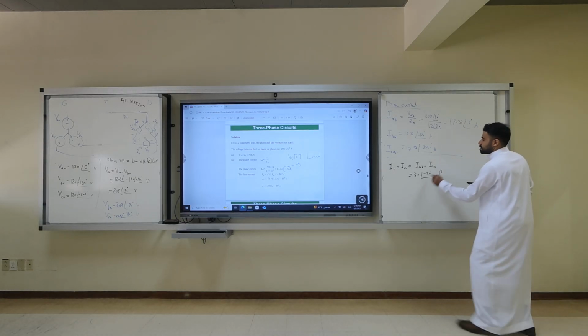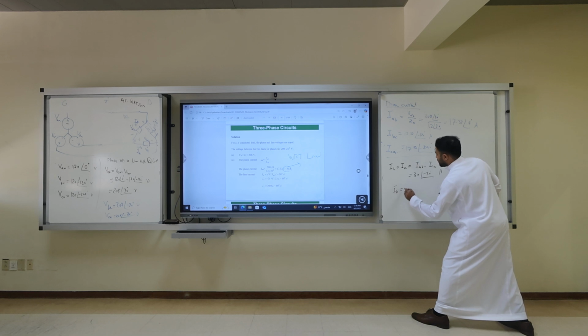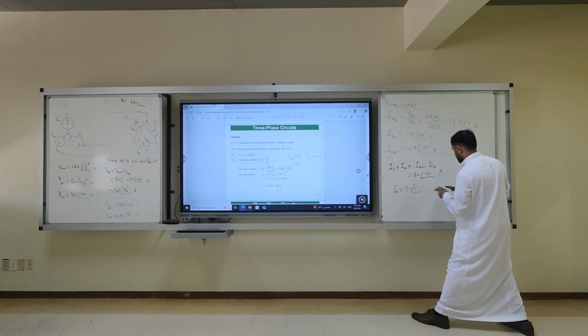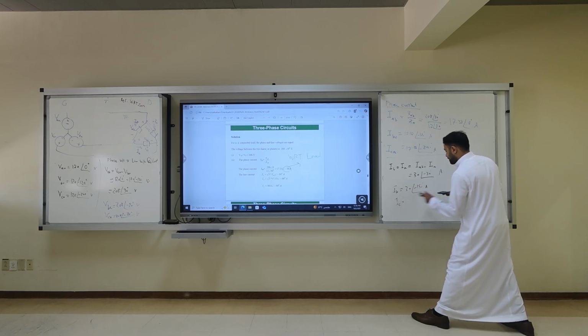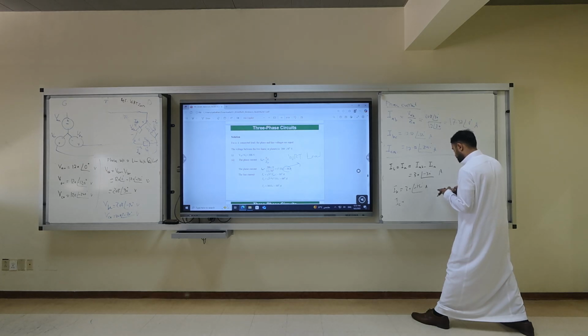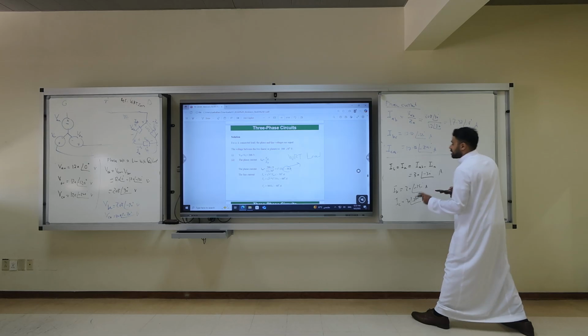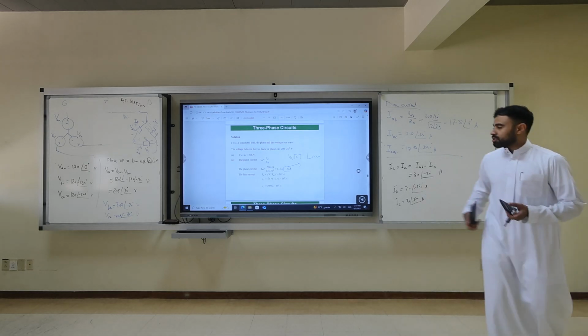Amps. So what is IB? It is 30 angle minus 30 minus 120, which is minus 150 degrees amps, and IC is 30 angle minus 30 minus 240, which is minus 270 degrees amps. So both approaches are correct.